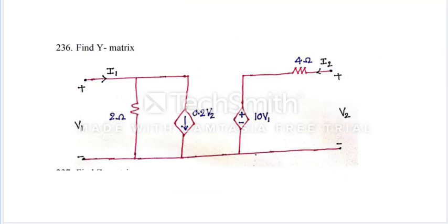Next, Y matrix, Y parameters. Y parameters we can do. Now, what we can do, you tell me here, how we can approach now, tell me, for this Y parameters. So, for Y parameter, generally we should approach for this KCL. If we write the KCL, that is nodal equation, directly we can get Y parameter. If possible, do, otherwise we will modify this thing. We can see here this one.